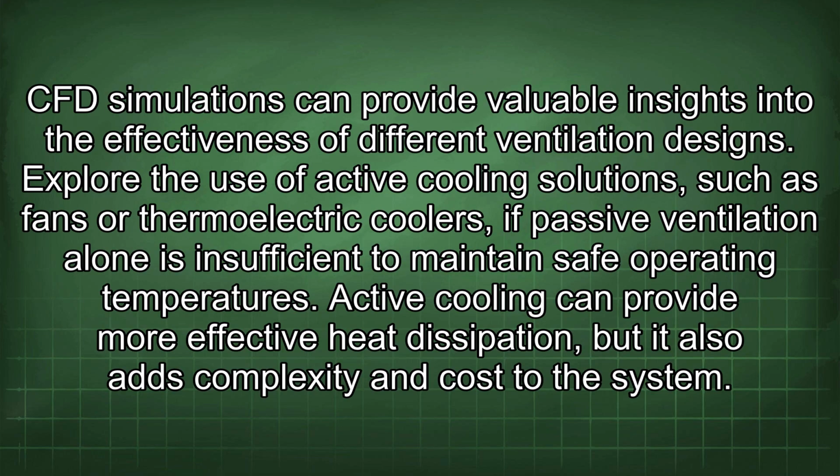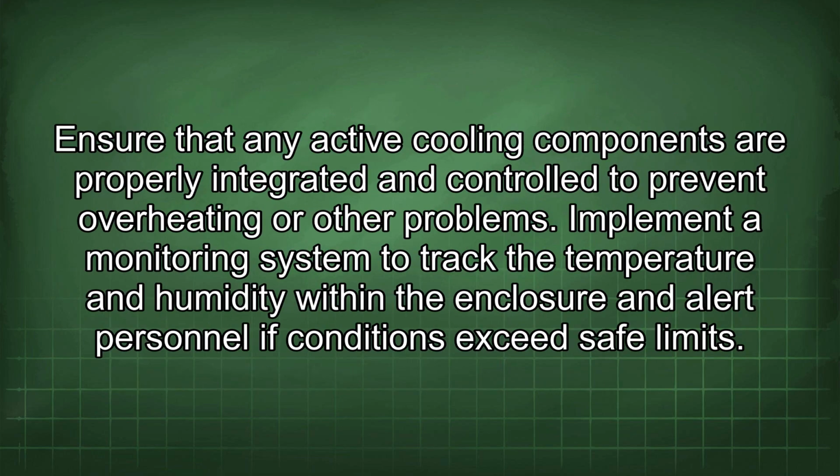Explore the use of active cooling solutions, such as fans or thermoelectric coolers, if passive ventilation alone is insufficient to maintain safe operating temperatures. Active cooling can provide more effective heat dissipation, but it also adds complexity and cost to the system. Ensure that any active cooling components are properly integrated and controlled to prevent overheating or other problems.